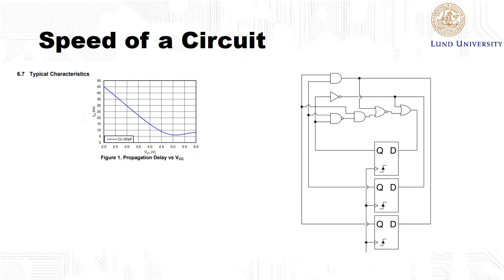Now imagine that you have designed a counter by implementing a finite state machine. It consists of flip-flops as well as a combinational circuit which generates the next state. How fast could you run this circuit? That is, what is the maximum clock speed you can use for the flip-flops? Well, let's assume that our flip-flops change value on the positive clock edge. The outputs of the flip-flops act as input to our combinational circuits. At the positive clock edge, flip-flops change value.